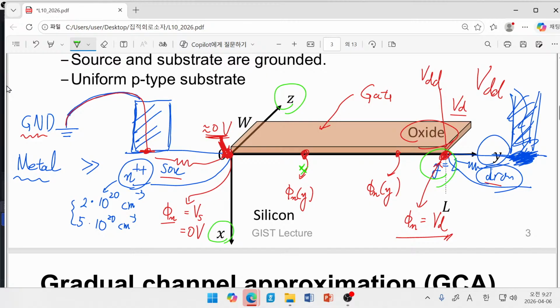In our planar MOSFET technology, this z direction is just working as the width of our transistor. By adding a wider channel, we just say that a wider channel has more conductivity due to the more width. So this z directional width is treated as just a secondary impact. So this is not that important.